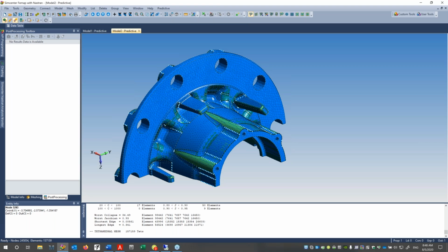But in FEA, you want small features. Small features lead to fatigue cracks and dangerous stuff. So the approach on the FEMAP team is that they keep all the small features, but they try to blend the surfaces so that your small features don't kill your mesh.